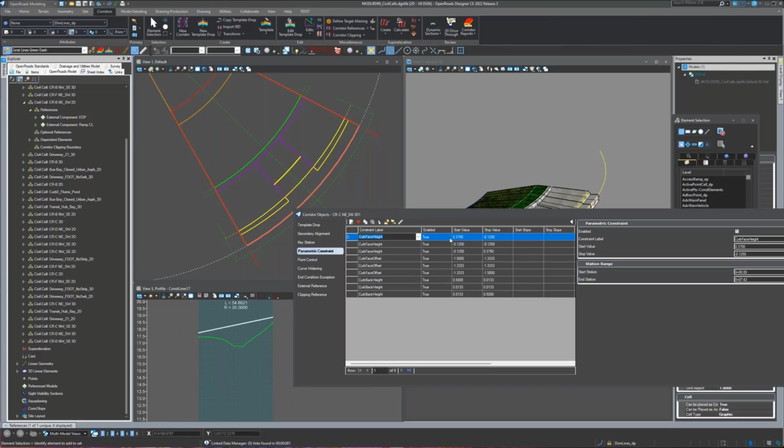And it's basically doing the same thing. We're going down full curb face height down to the gutter, at the gutter level through here, back up to the full curb face offset. We're going from our normal offset down to the gutter offset, staying at the gutter offset, and then back up.